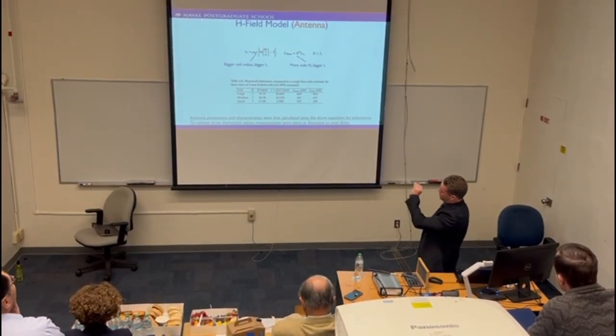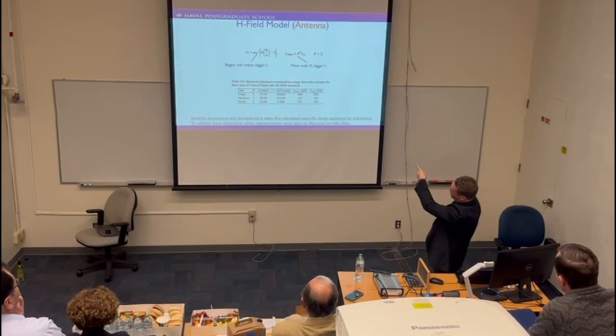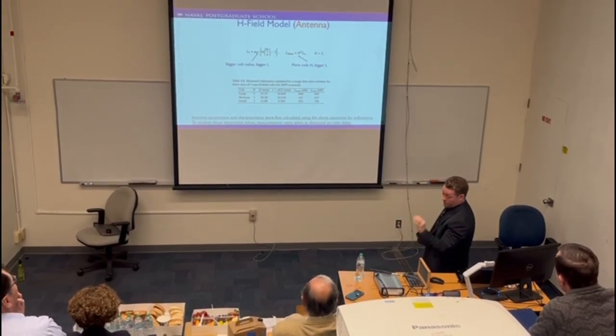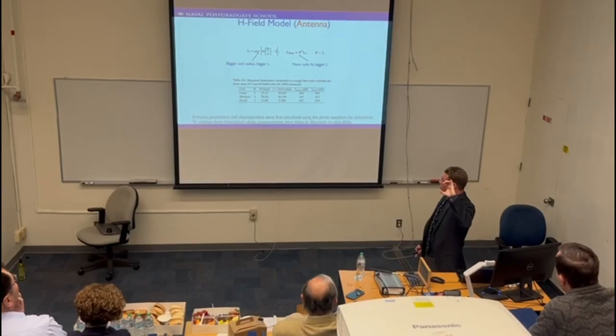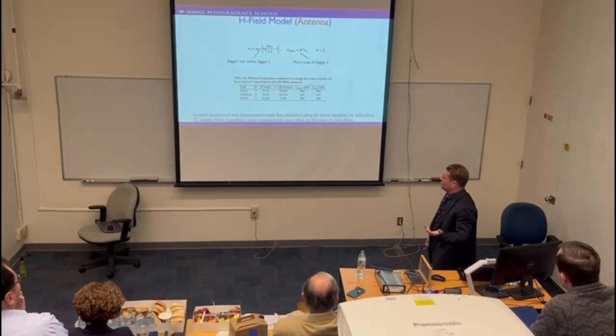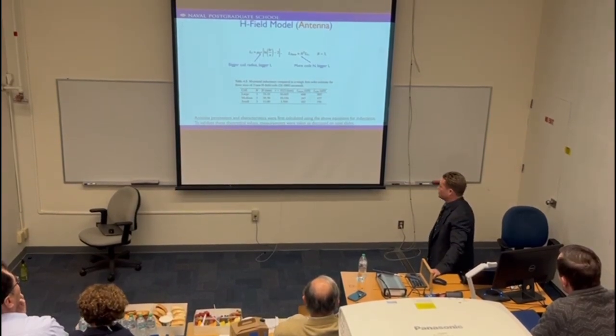And as that radius changes, you can see it's directly proportional to inductance. The big R changes, or the smaller changes, you get bigger L. So a bigger diameter loop has more inductance, smaller has less inductance. And then obviously the number of coils you have too. If I have, say, 3 turns, I'm going to have more inductance than just 1 turn.